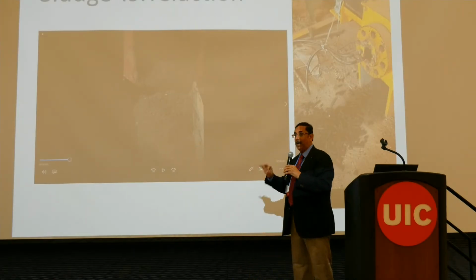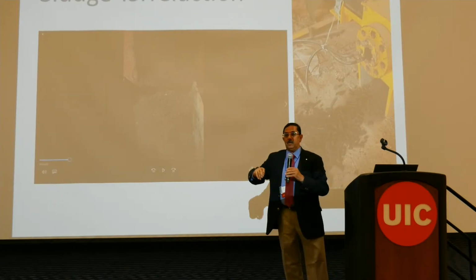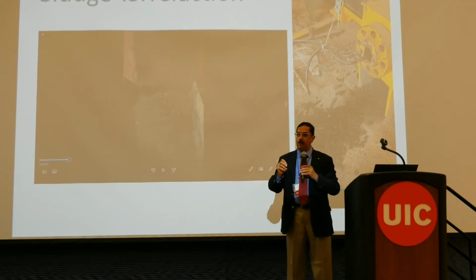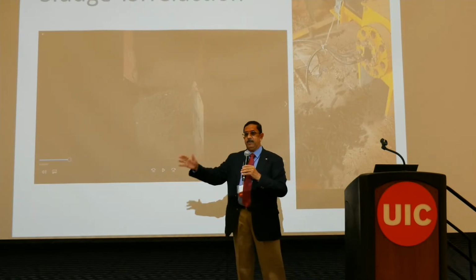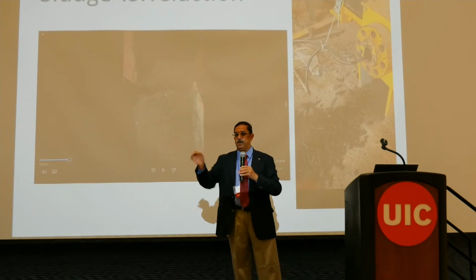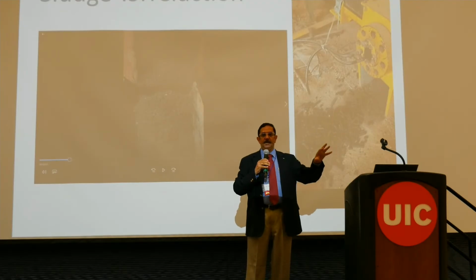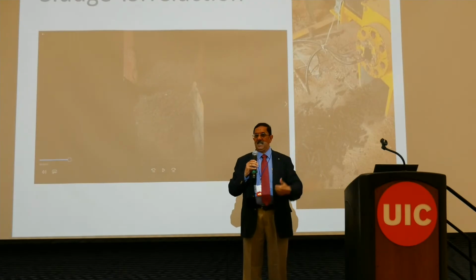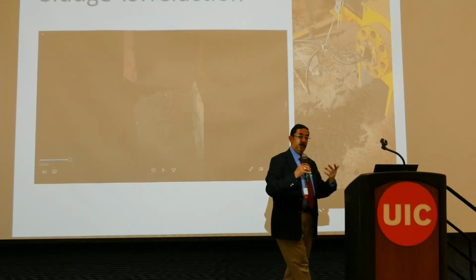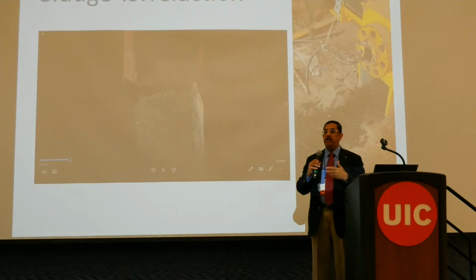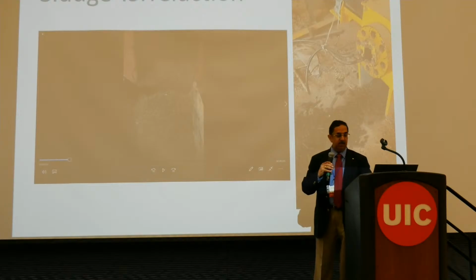So it has to be made into pellets. So we looked at how to do pellets. And the problem was, we couldn't use anything else. We had to use a small amount of water, so that reduced the kilocalories per kg from 2500 to the 1900 to 2100 range. But that was enough for the thermal power stations. So we shipped almost 150 tons of this pelletized sludge mass to them, and they fired it for almost 10 days to see how that effectively works when coal substitutes are needed.